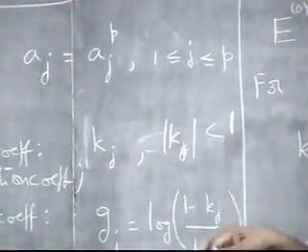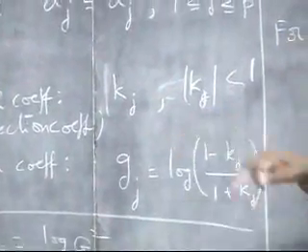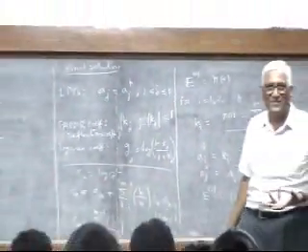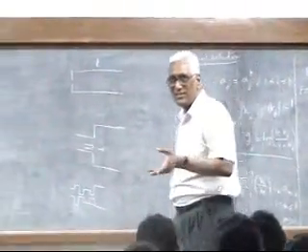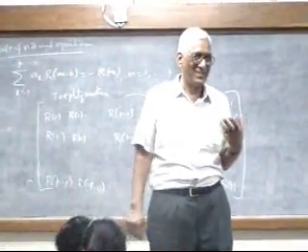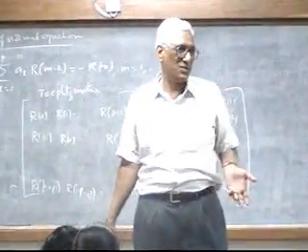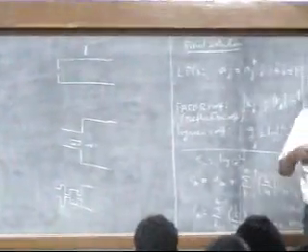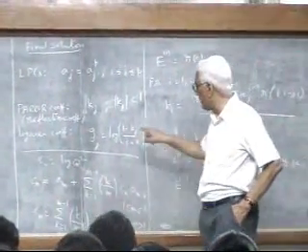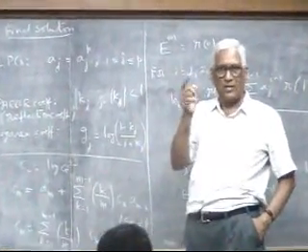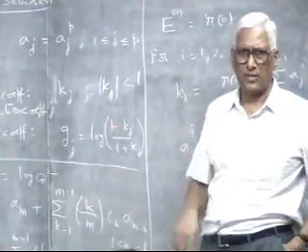And from that Ai by Aj, you can define the log area coefficient. Why log area coefficients? It so happens, again, take your cell phone, this is what is used, or something related to this is what is used for coding, because of the stability of the coefficients and so on. Otherwise, I should have written an intermediate step, what are called the area coefficients. Area coefficients are nothing but this ratio related to K. You can look into the books for that. So there is no problem.